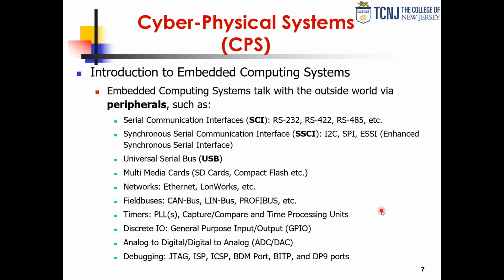Then we have what is called field buses, which are very much used in cyber-physical systems and devices to network and connect a host or a master to distributed actors throughout the system. So I'm talking off board. So the controller area network bus, the CAN bus, very much used in automotive for the middle tier network.